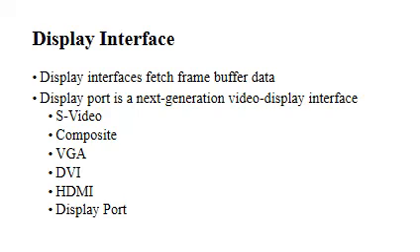Last one is DisplayPort. It looks very similar to HDMI but has only one corner left. It has 20 teeny pins around a central plastic strip that is like USB. It is becoming more widely used in computer monitors. The DisplayPort signal is not natively compatible with DVI or HDMI.